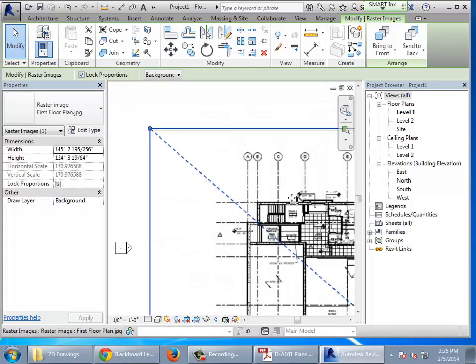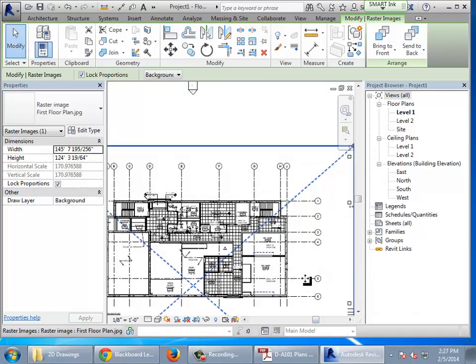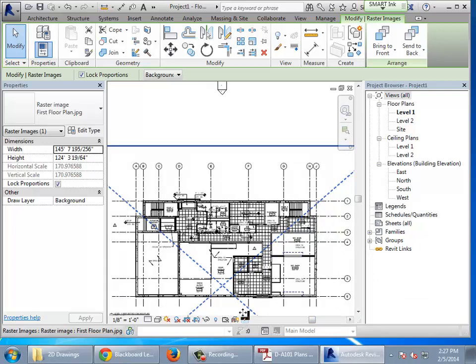So does anyone have a dimension that we can use? For example, in one of the other drawings, you probably have a dimension between grid line 4 and grid line 5, or if you happen to know the dimension all the way from A to J, that's a really good one because it'll be a really long dimension and will scale very accurately. When you do this, try to get the longest thing you know a dimension for and scale that, because trying to scale based off of a few feet, you have just the inaccuracy of the pixels. So on this building, how long is that building from A to J? Can somebody measure or find out from A to J? Is it 119? 119 feet, even? And 8 inches. Okay, 119.8.